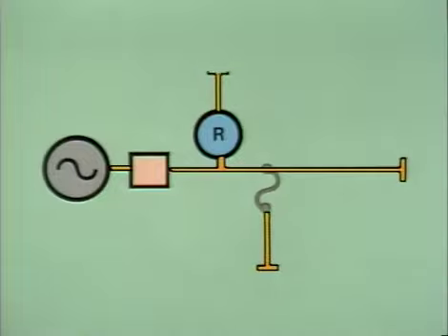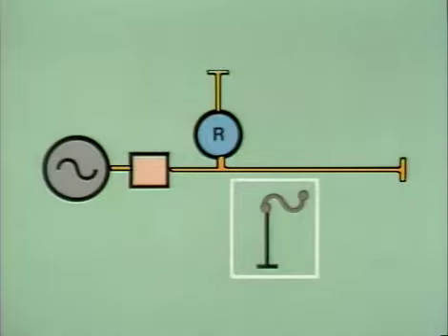Now, like most electrical hazards, faults can occur almost anywhere in an electrical system. Suppose a fault develops here. The current in the line increases rapidly. When the current gets high enough, the fuse opens to break the circuit. This de-energizes the branch line, but protects the rest of the electrical system from the fault. Therefore, in addition to protecting system equipment, the fuse helps the system continue delivering power to the remainder of its customers.